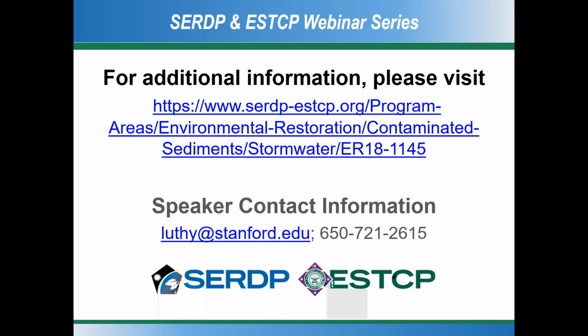And I just want to emphasize again, our predictions about performance in the field look really great, but you have to have some pre-treatment to prevent clogging of your filters. In other words, these filters can't act as particle traps. If they act as particle traps, then you'll have short runs because you'll form a particle layer in your filters, and then the water won't be able to flow. So there needs to be a sedimentation basin or maybe a coarse sand filter to remove particles before it goes into this kind of device.